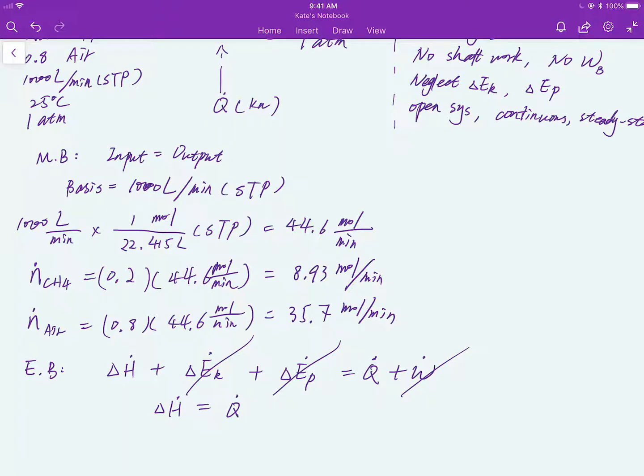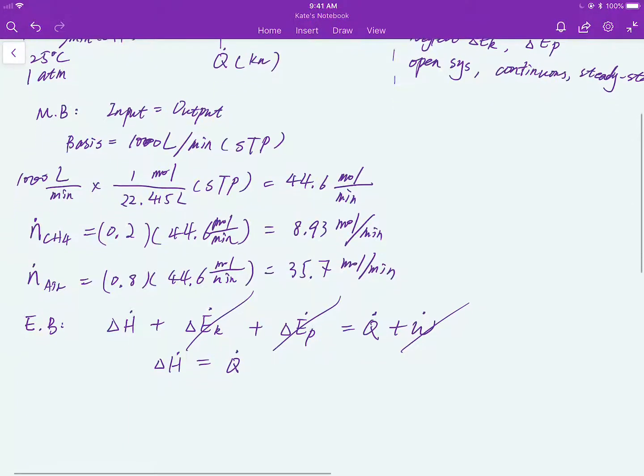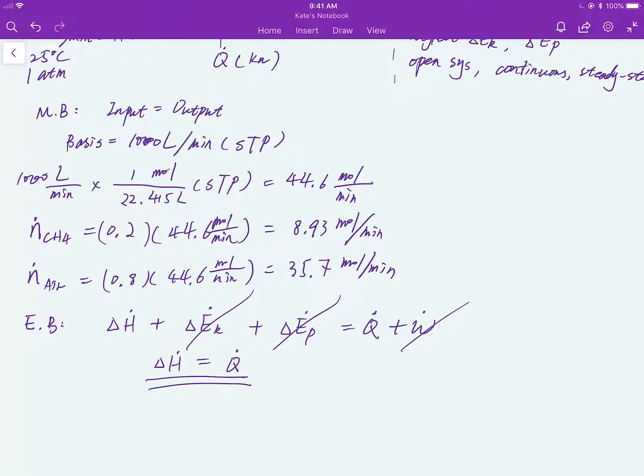And this is about heat flow. Then we can start from there. We know the enthalpy change equals mole number, because this had the units kilojoule, right? And then we had to use mole number times specific enthalpy change, and specific enthalpy change had the units kilojoule per mole. And then I can use heat capacity to calculate specific enthalpy change.